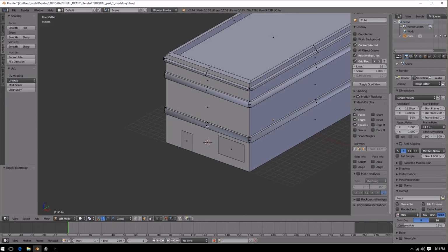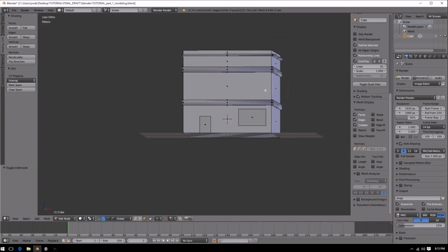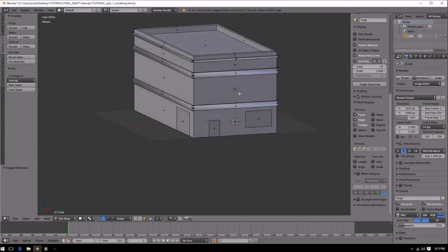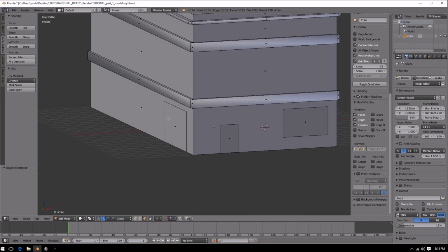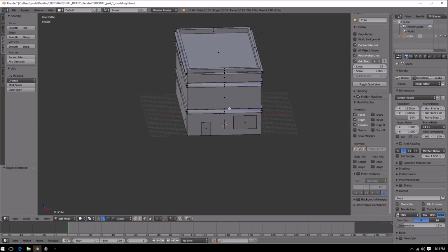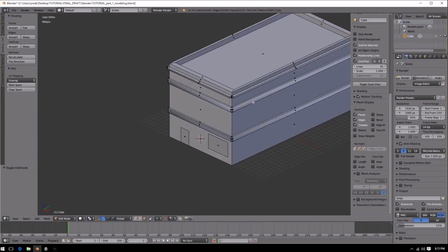And one thing that I'm definitely keeping an eye out for here is my tri count. And up in Blender you can notice this up here. I've actually targeted this for about a 300 tri model. It's going to be super tiny, and I'm doing everything I can to keep these tris down as well. I don't want this tri count to get as high as I can make it, just because I can make this 1,000 or 2,000 tris. I mean, some people do, but I tend to try to keep my assets as low as possible.